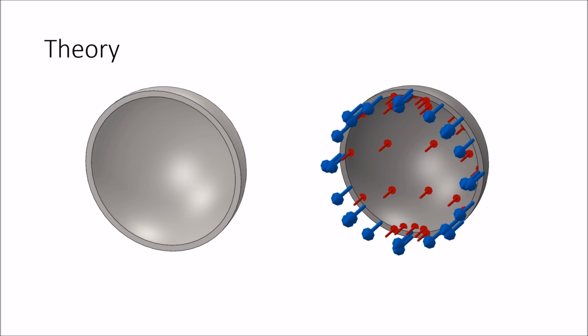Now if we look at a spherical end cap, we notice that there's a lot more material, but also a lot more area that is being covered. But what we should notice that is important is that we have twice the amount of material holding it together, because you have both sides resisting, not just one side of the pressure vessel. That is key to understand why this equation becomes PR over 2T.